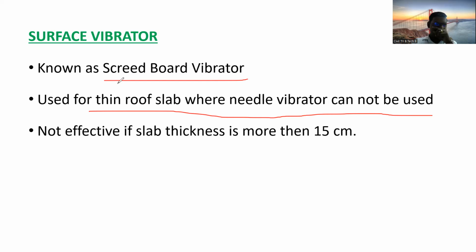So for this purpose we are using this particular surface vibrator. This surface vibrator is again not effective if the slab thickness is more than 15 centimeter. So this is required only for thin layers. Where thin layers of concrete are there, we are using this surface vibrator. But if the depth of your slab or your road is more than 15 centimeter, there we cannot use it.